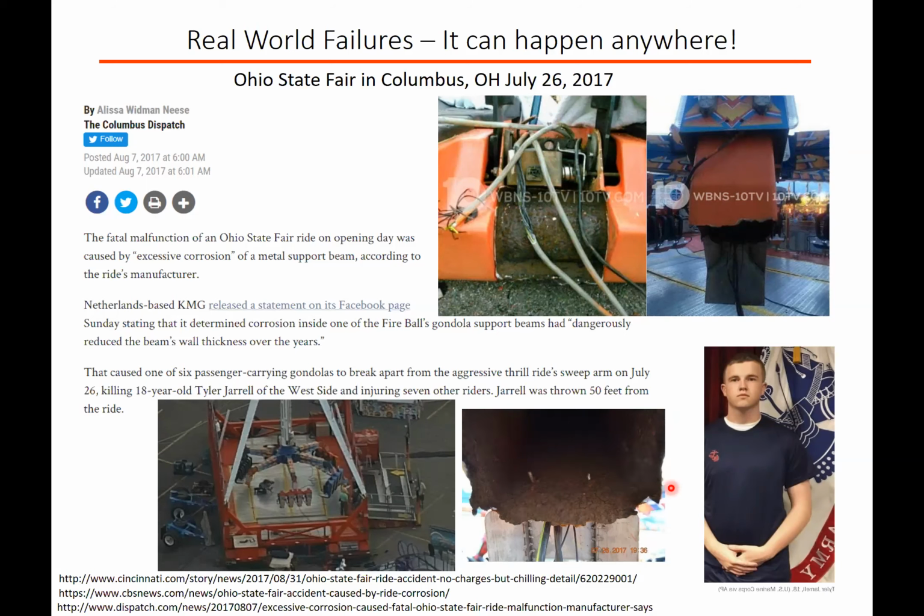When they took it apart for analysis, what was understood to have happened is that the walls were thinned due to corrosion, and that of course couldn't support the applied load, and it had obviously passed inspection initially. That was not the case anymore. What I know is from the public releases, but that's something we can learn from as well: corrosion and thinning of materials can have quite catastrophic results that are pretty close to home.